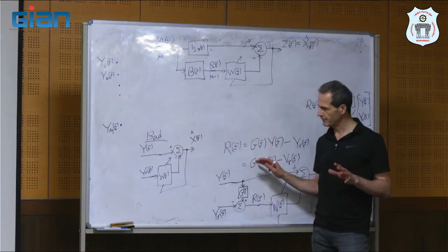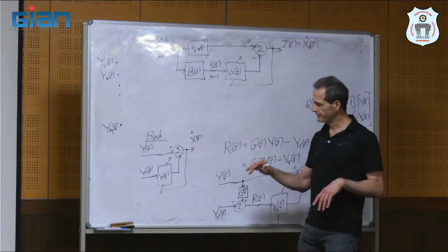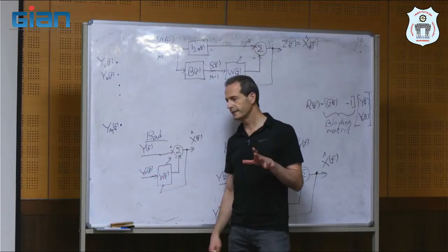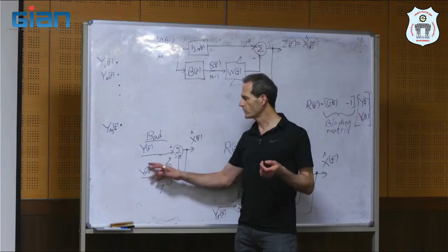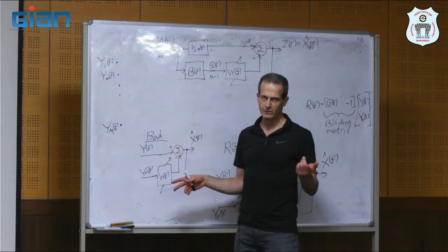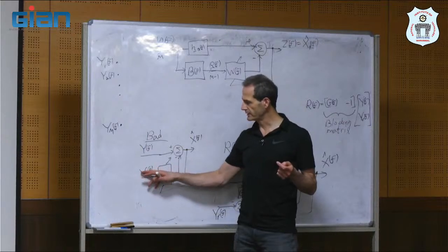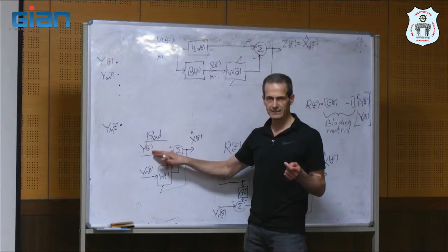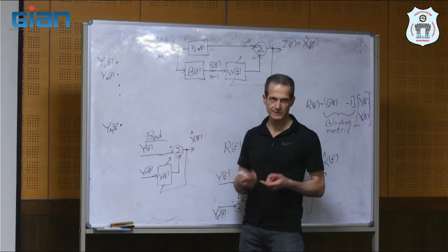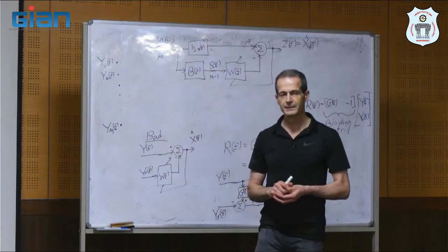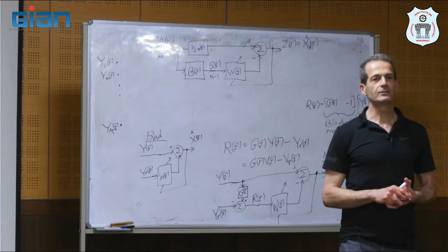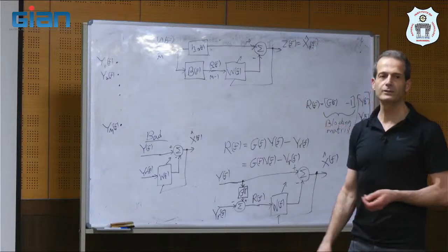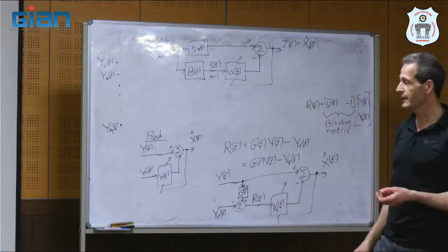But what they did in the past, they ignored this part, and they assumed that with the other microphone, we have only the heart rate of the mother. So why don't we just subtract one from the other? Because it's not the same, okay? The heart rate in the other sensor is not the same as the heart rate of the mother in that signal. But they correlate, to the same heart, the same source, okay? Same source. This is how they initially did that. So that was one of the early uses of adaptive filtering, which is nice.